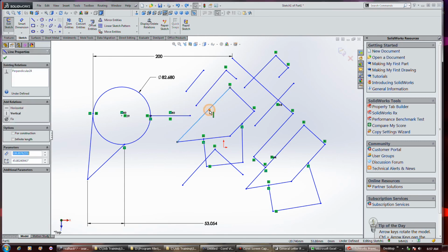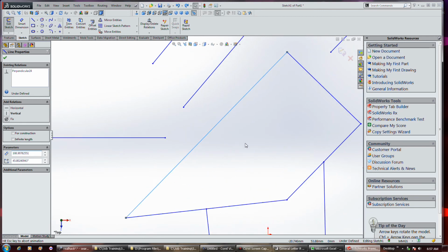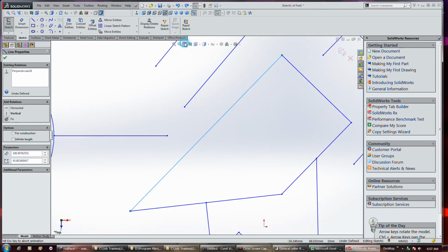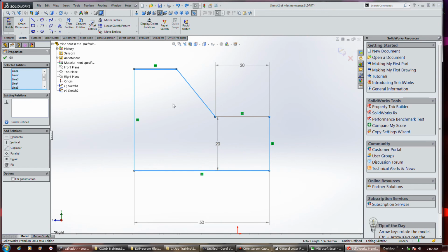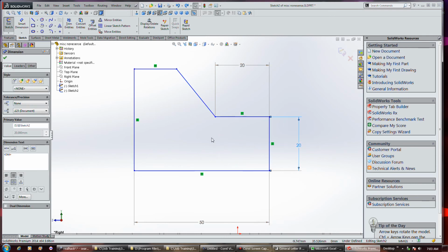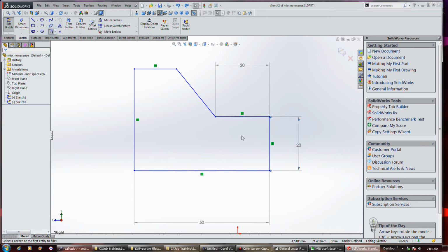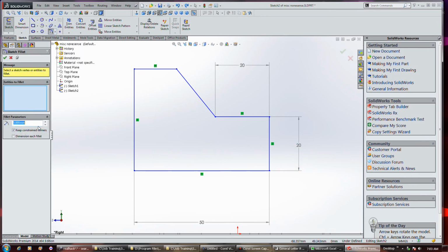Possibly a little interesting little tool here is this zoom to selection. So thought I'd mention that. More often than not, when I'm drawing, it makes more sense to, rather than trying to do that stupid arc thing, which gives me all kinds of a headache, and then you can't define your geometry because usually you just know the outside dimensions of it. Like you see here, it's better just to draw it with straight lines, and then come in and define a fillet with a known radius.